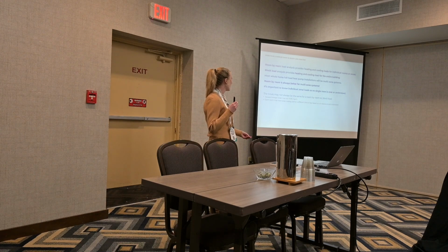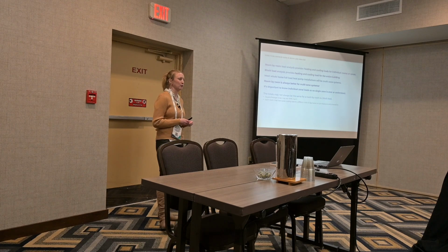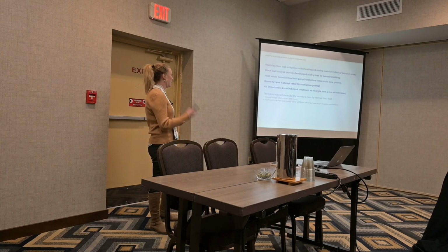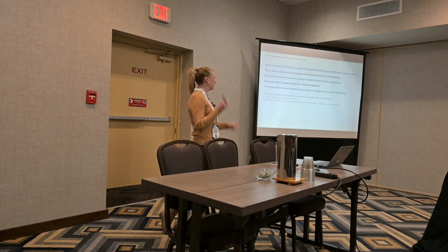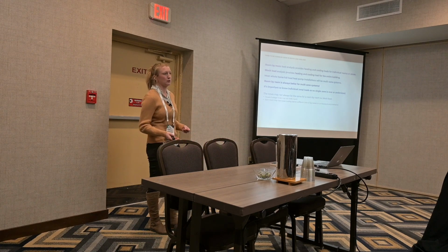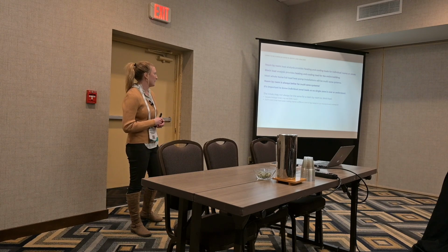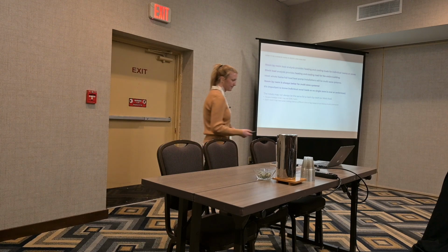You might come across that the totals may not always be the same if you check and do a room by room and a block load. That's just because square footages might not always match, and peak heating or peak times of the day for cooling load are going to be different depending on the room. So that's just another tidbit fact. But really, we recommend always doing a room by room load sizing analysis for heat pumps.